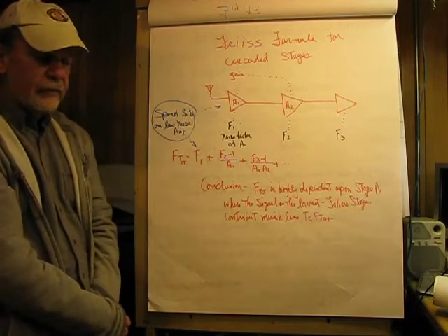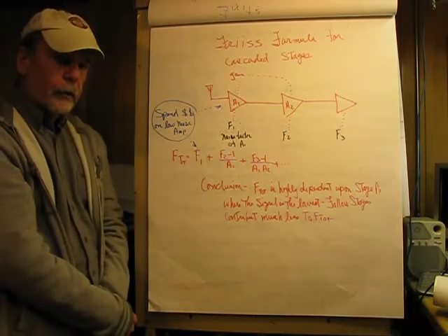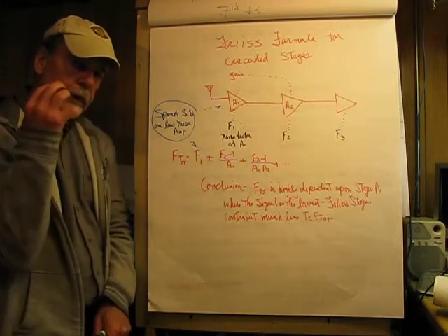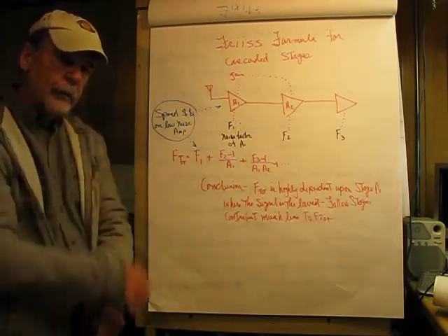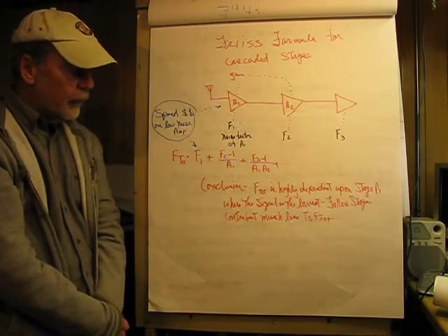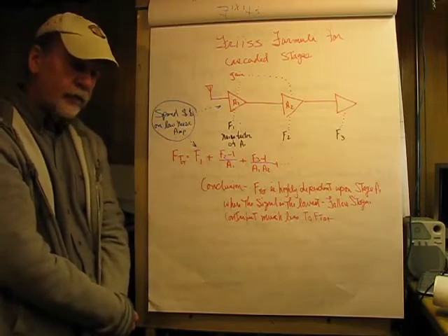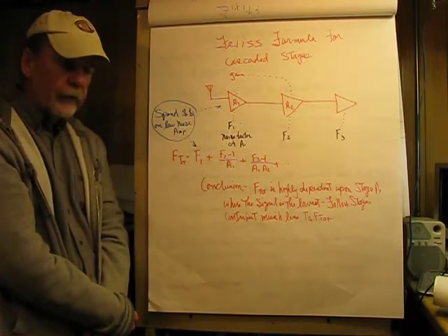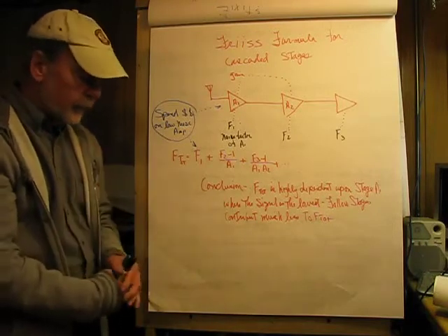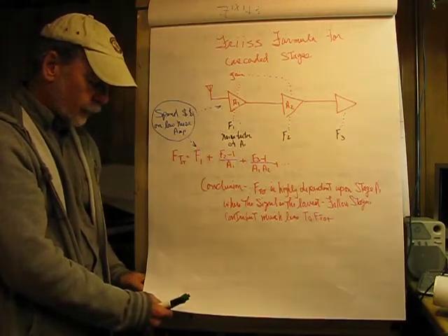Now on DirecTV dishes, the actual low noise amplifier or low noise block converter is sitting in the feed device on the dish, right outside of it where the cable's mounted. Because that way you don't pick up any loss of the cables, like in that previous example with the 6 dB that you can't make up. So right off the dish, right in the feed device, that's where the low noise amplifier or low noise block converter is located.